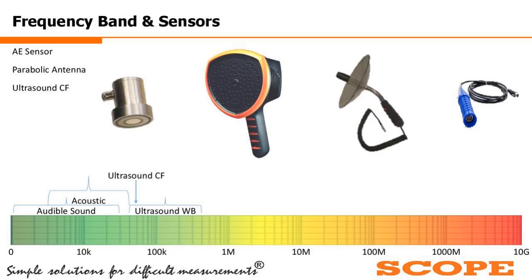So this is your acoustic emission sensor. This sensor, as you are seeing over here, is a contact kind of sensor. These are commercially available. The outer linkage that you are seeing over here, the black linkage, is generally magnetic. So on any grounded metallic body like a transformer tank, switchgear panel, or dead tank kind of circuit breaker, anywhere you have metallic grounded panels, you can stick these sensors on the body, and with the help of this connector and a cable, you can always take readings. So this is one contact kind, and the rest are all non-contact kind of sensors.